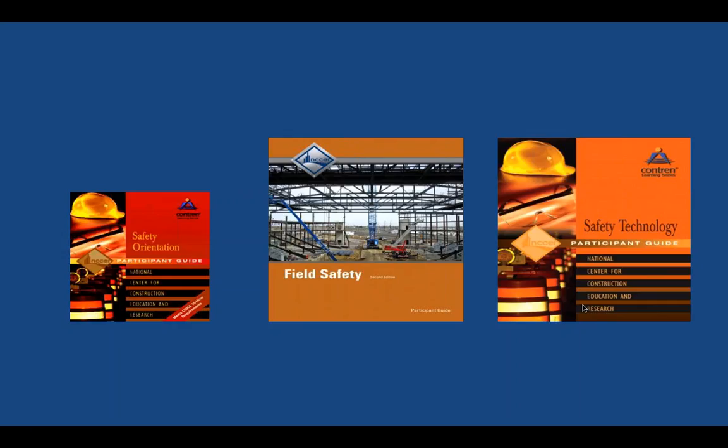Okay, so maybe let's use guardrails. Perfect example. Let's say a scaffold, and we have a top rail and a mid rail. We still use fall protection a lot. So even though we've got top rails and mid rails, and that scaffold may be perfectly legally acceptable, even though the front may not have a guardrail system, we're close enough, usually within 14 inches of the surface in front of us. It's got all guardrails on there, top rails, mid rails, toe boards, and there's not a significant risk of somebody falling, but we still require them to use personal fall arrest. You see where I'm going?